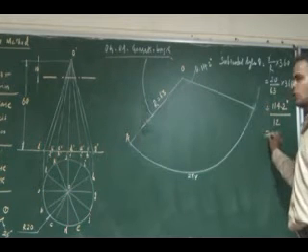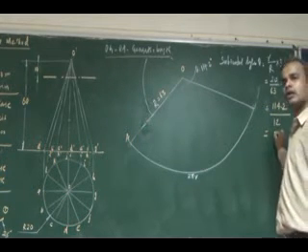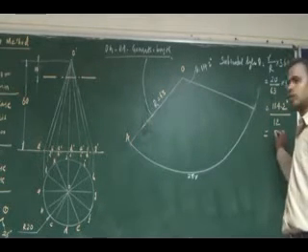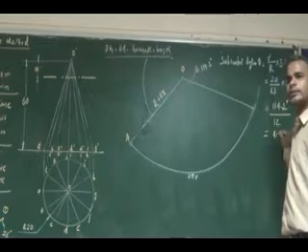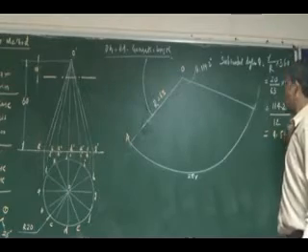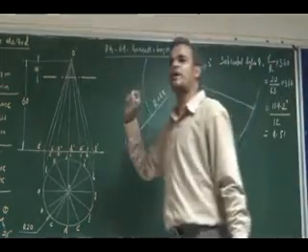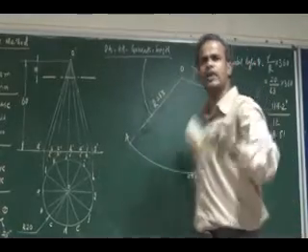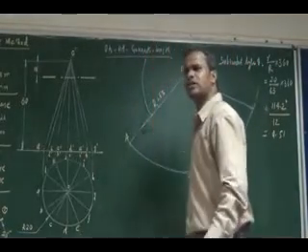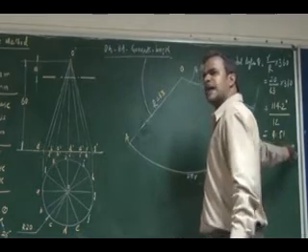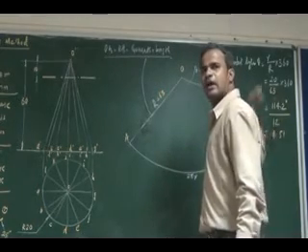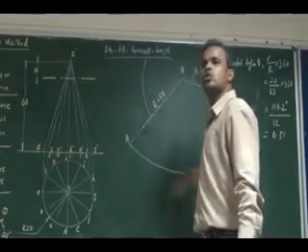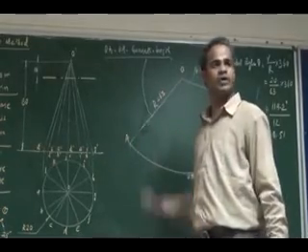For 12 divisions, you will get 9.51. So for 9.51 degrees, you have to get 12 divisions. Listen all of you, from your exam point of view, you measure this angle 9.51, and that is the right procedure. Similarly, you measure this angle 114 degrees, then you get the development of the cone. That is the right one.